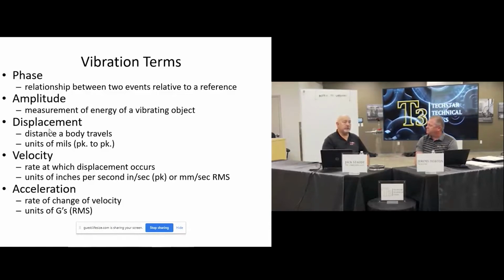That really depends on what type of accelerometer you're using, if you're using a MEMS or an ICP type accelerometer too. Oh, so that makes a difference. Yeah. I'm not from the diagnostic world like you are, but that was always a question I had: a single sensor mounted in one plane, a lot of times in the vertical plane. How effective is that one sensor at measuring a horizontal vibration or an axial vibration from that single plane? In your opinion, do you get good quality data?